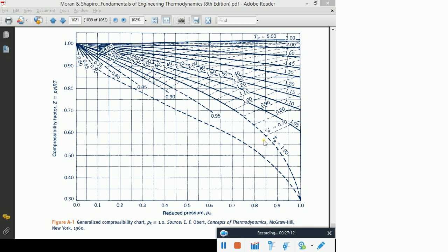So you want to find out the value of pressure in this chart in terms of reduced pressure. What you can see is you have TR equals 1.04. So obviously this is the line for 1.05, so it should be very close to it. It may be somewhere here, very close to it. And then you have VR equals 1.12. So you may be having that value somewhere here, where the cursor is. Okay. And what is that value? PR is almost 0.7.